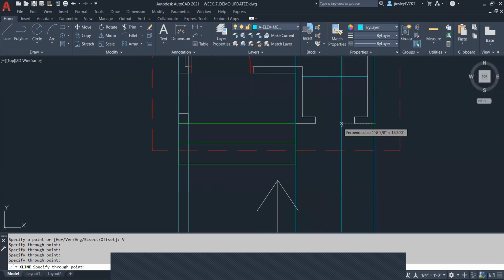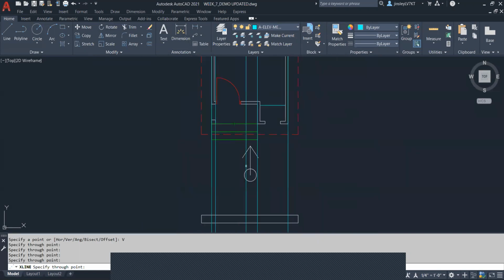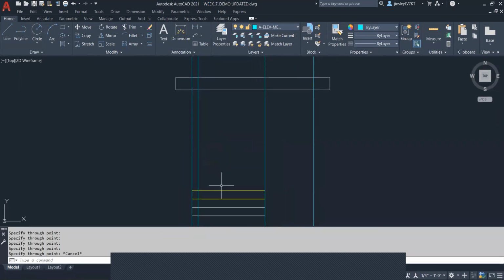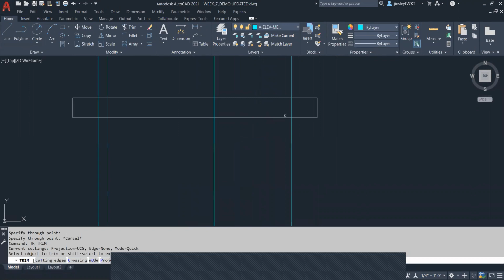The window, I'm actually going to draw on the fine layer, because if you put your window mullions on too bold of a layer, they don't look crisp and they can actually look a little bit messy. So usually any bits of detail I will put onto a fine layer so that it stays nice and sharp when we print.